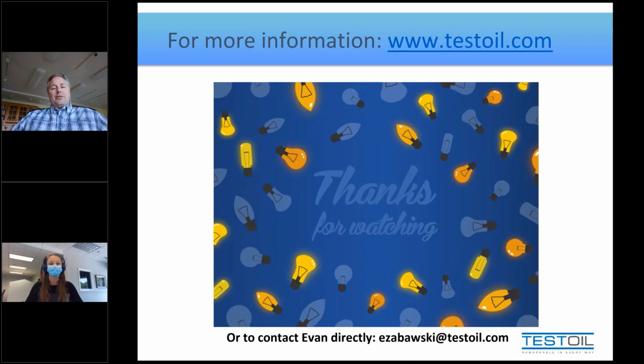The only issue you're going to have is that the viscosity will read low, and that's just expected. As long as you consistently take the samples and we consistently test them with the refrigerant, we can still trend that viscosity and tell you if there's an issue. If we were to consistently degas it, whether the customer or the lab did it, we can still trend that too. But I'm just not in favor of doing it that way. I don't see much logic in needing to remove the gas just to see the viscosity in a perfect state, which it is not when it's lubricating equipment anyway.